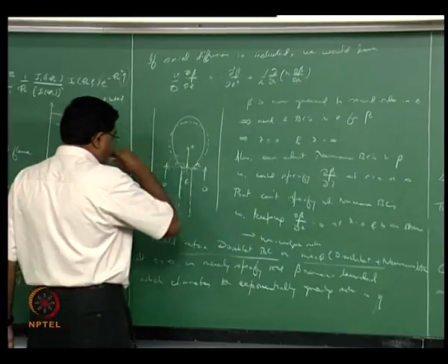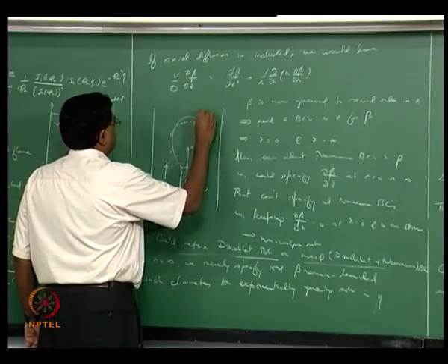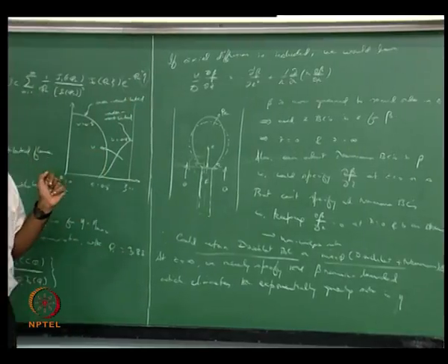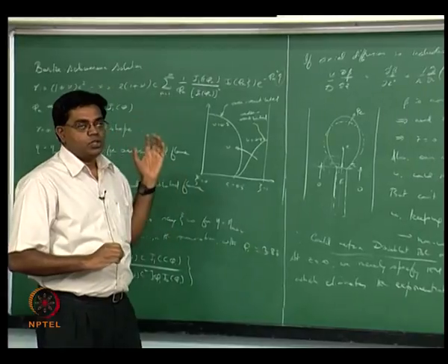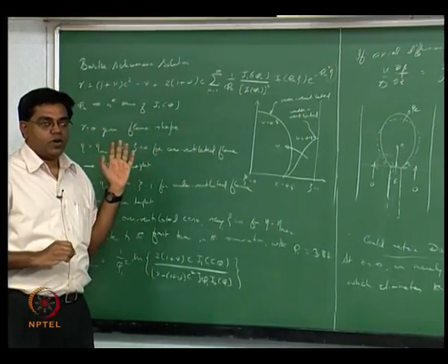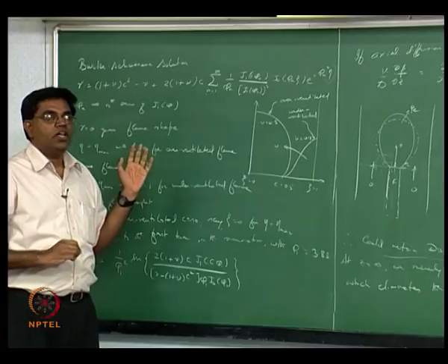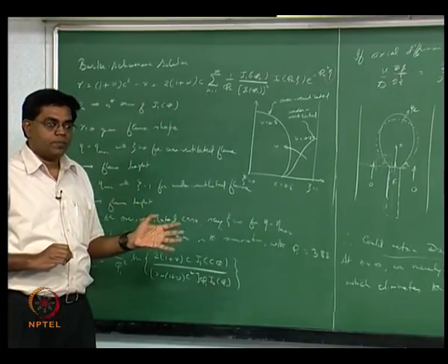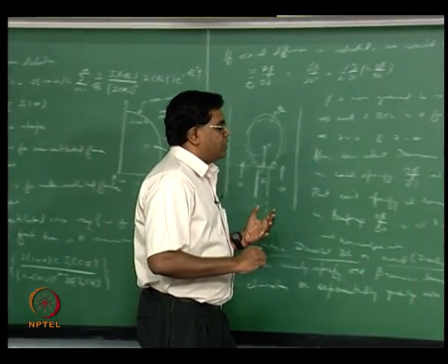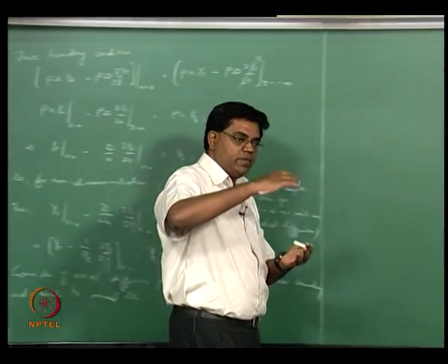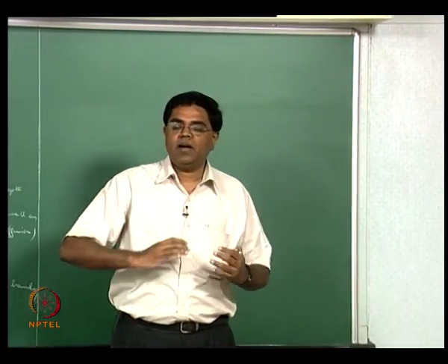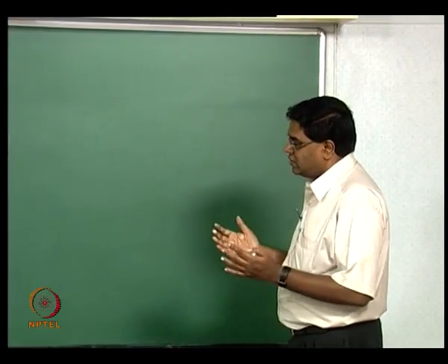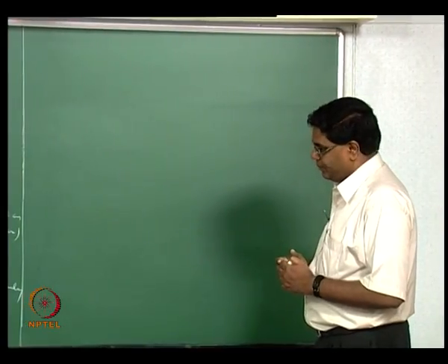So this is the way you're going to get things to go as Peclet number increases. And the Burke-Schumann solution that we saw so far, neglecting axial diffusion, is in the limit of infinite Peclet number. Alright, so the job of axial diffusion is to make the flame shorter, because you have more mixing happening axially as well as radially, and therefore you get a shorter and a bit fatter flame correspondingly.